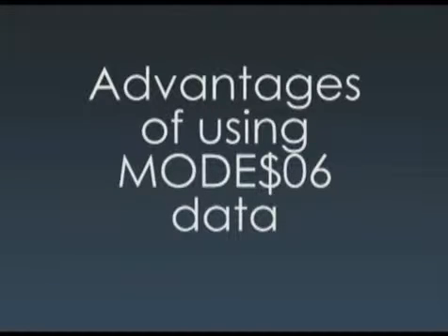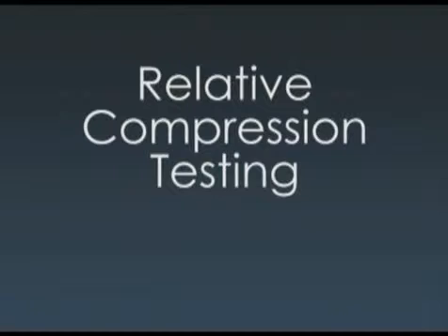Without Mode 6, we would have had to connect our scope to each cylinder and try to get it to act up, or guess at replacing all 8 coils and hope that the truck was repaired. The Mode 6 data made it a quick, clean, accurate diagnosis and a clean verification. The relative compression test with a scope only took a few minutes and ruled out the base engine as the cause of the misfire and more costly repairs.